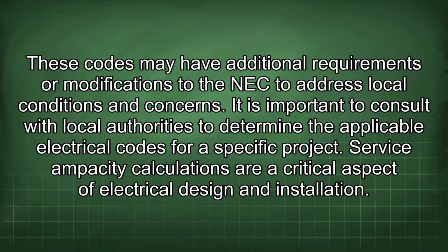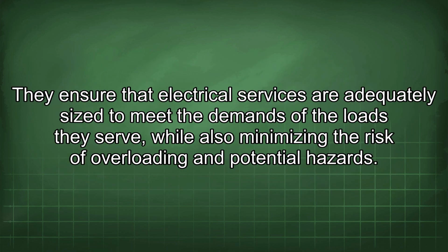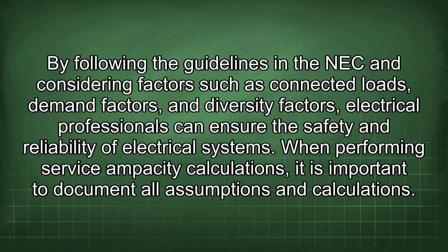Service ampacity calculations are a critical aspect of electrical design and installation. They ensure that electrical services are adequately sized to meet the demands of the loads they serve, while also minimizing the risk of overloading and potential hazards. By following the guidelines in the NEC and considering factors such as connected loads, demand factors, and diversity factors, electrical professionals can ensure the safety and reliability of electrical systems.